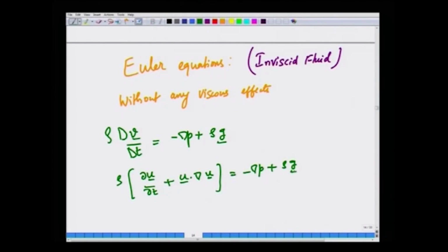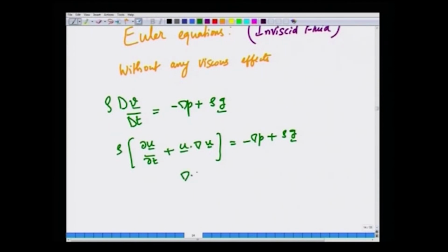So, this is the Euler equation in conjunction with the continuity equation. So, this is for an inviscid or frictionless flow, or a flow of a hypothetical non-viscous fluid. Of course, there is no fluid that in reality has 0 viscosity, but we will see a little later that in some regimes we can assume that the viscous effects are negligible compared to other effects such as inertial forces or pressure forces.